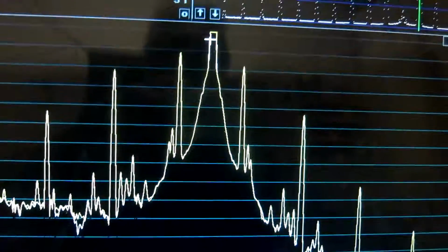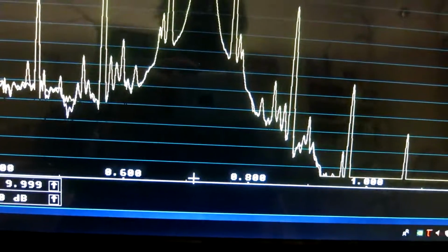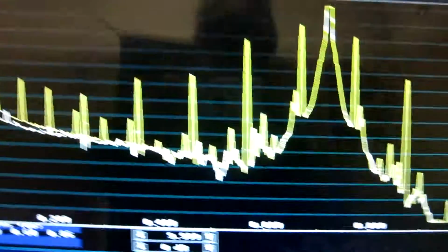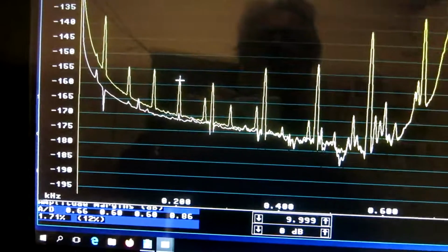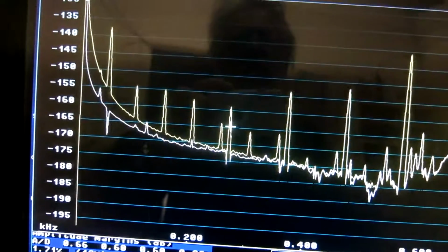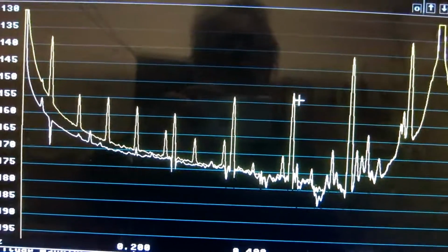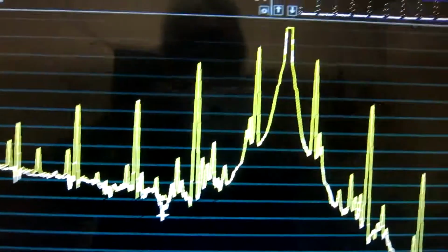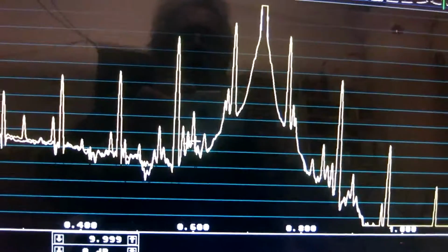I have moved the 700 Hz a little bit higher. You can see it is maybe 710, 715. And that means that overtones from 50 Hz, 50, 100, 150, 200, 250 is here. And this is the sidebands from the DC. Means 50, 150, 250, 350 from the zero peak. So I have moved the problem with the sideband, with the noise from this DC a little bit further up.